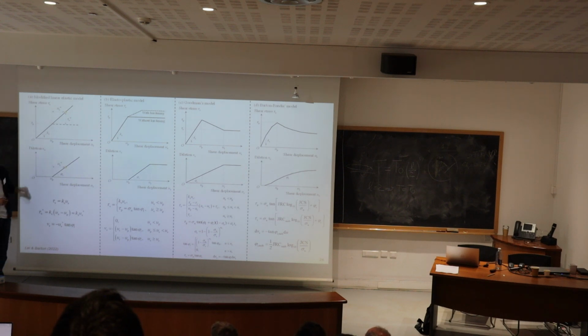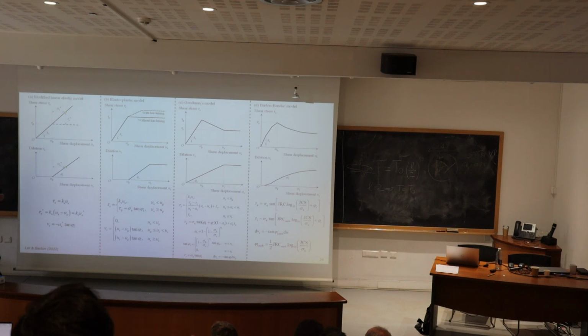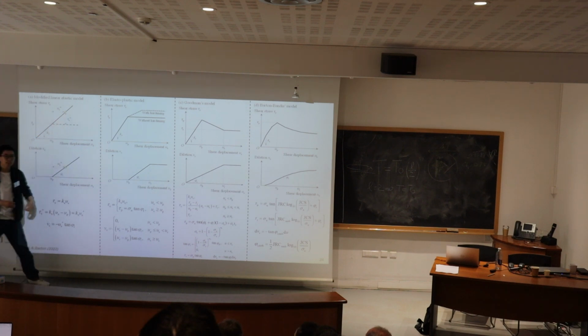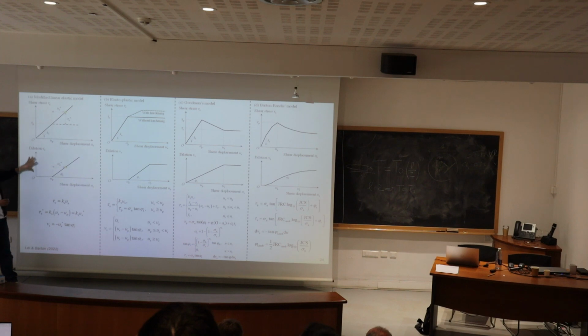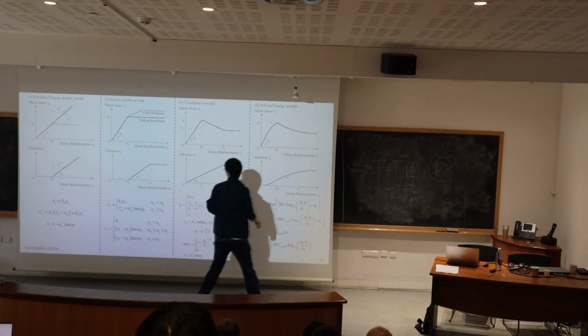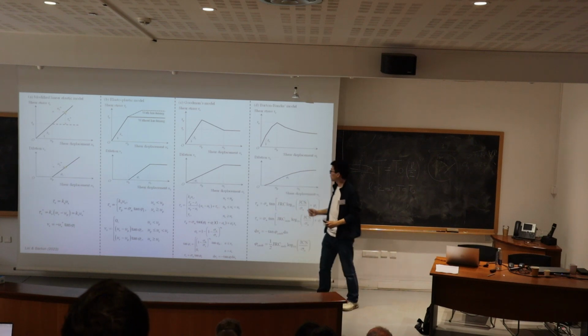This can be embedded into linear elastic simulators like the finite element method. But the tricky thing is that the actual shear stress can go much beyond the plastic shear stress. So although it has very good convergence, it may not be a good model to capture the full physics.